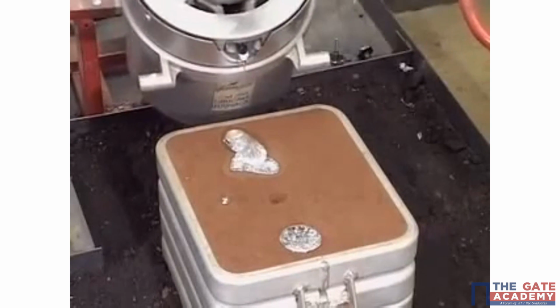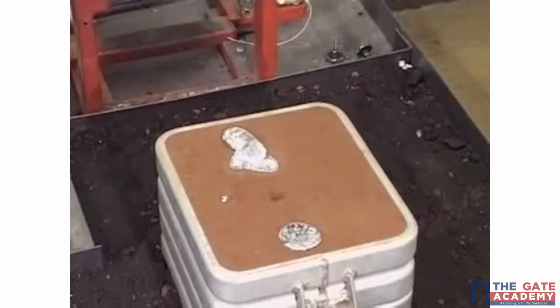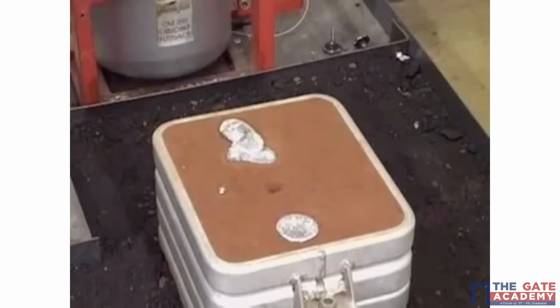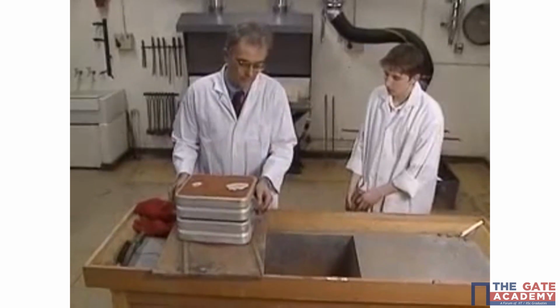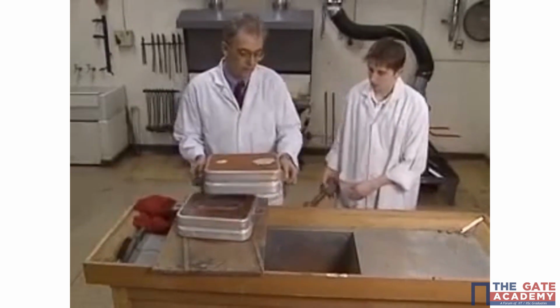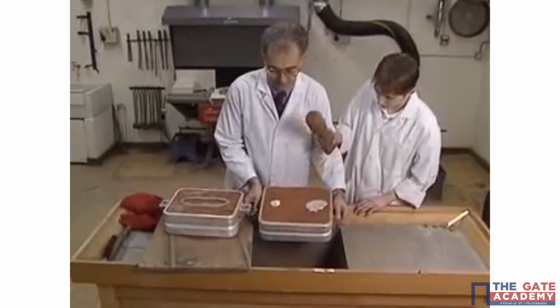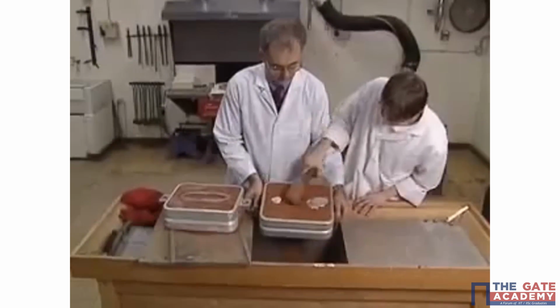Actually that is nothing but the riser. When the molten metal came out of it, we immediately stopped pouring, because it was an indication that our mold cavity has been filled up, right? It is just an additional function, my friends. It is not always the case, okay?